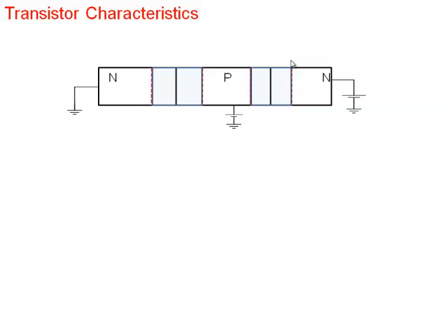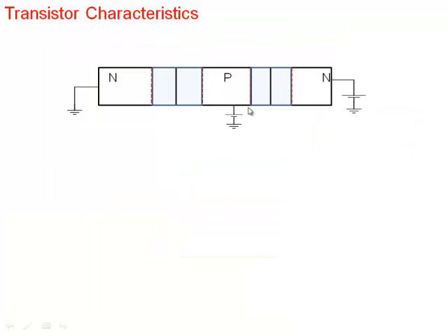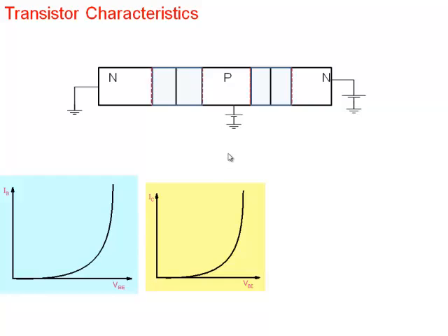All right, so I'm showing the same things now. I represented the transistor in one way. This is another very common representation of the transistor. In terms of graphical picture, let's see if this makes sense. This is my base current here, and this is my base emitter voltage. Does it make sense that it has a characteristic like this here? Because base current is what? Hole current, and it changes exponentially with base emitter voltage here. So that's my base current versus base emitter voltage.